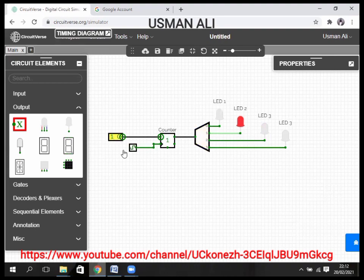Now when we increase our max value to 3, the counter changes value 0 1 2, then 0 1 2. Because max value is 3, the counter goes from 0 to 2, three numbers, then the decoder decodes it, and our 3 LED lights are turning on and off sequentially.